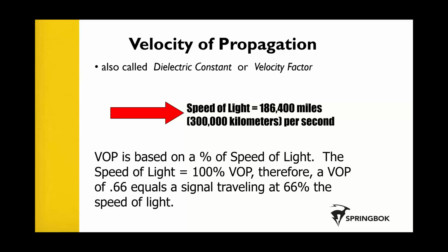It has to do with the type of cable that you are testing. Every type of metallic cable out there has at least a 2-digit VOP number that's associated. When I say at least 2, I mean sometimes it's 3. I don't care whether it's RG59, RG6, half-inch, inch, 2-aught power cable, 22-gauge twisted pair. There's at least a 2-digit VOP number that's associated with it. And this is all that number means.